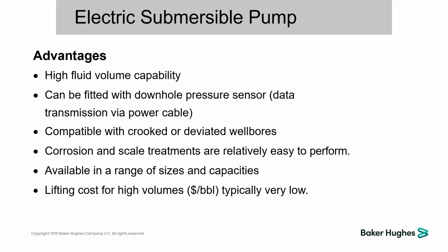In terms of corrosion and scale, ESP can work with chemical injection, either a separate chemical injection or one combined with the ESP. That's one of the advantages for ESP. In some other artificial lift, such as PCP, you cannot inject downhole chemicals because that affects the integrity of those artificial lifts, such as through the elastomer effect.